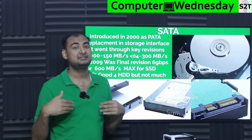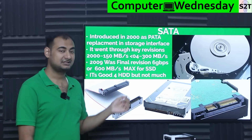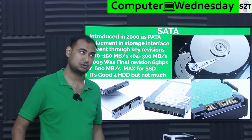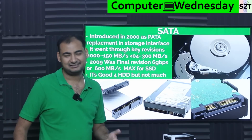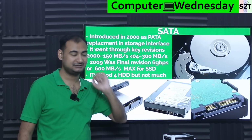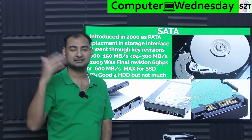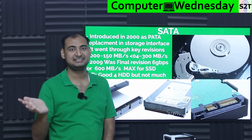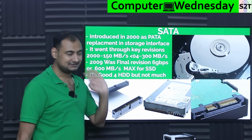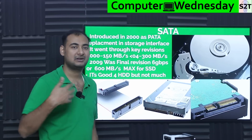We have increased capacity exponentially, but in terms of throughput, that's still stuck. Meaning, if you have SATA 2, even if you buy a modern 22 terabyte hard drive, it still has the same speed. Actually 250 megabytes per second read and write speed, and that's sequential, meaning you read from one continuous spiral going outward, almost like a CD or DVD. Then you can get that speed. But if it's random seek and write, no, you're not going to get that speed. So SATA 2 was kind of the upper limit, where they had already exceeded what they were made for.